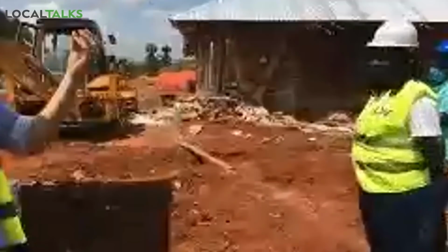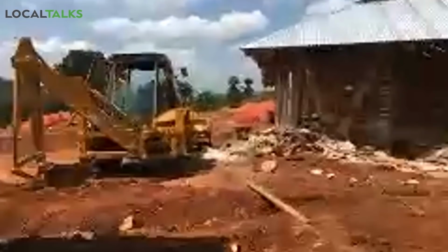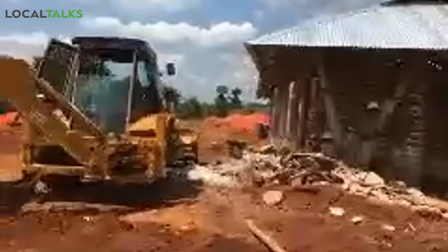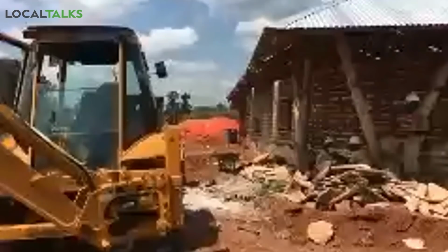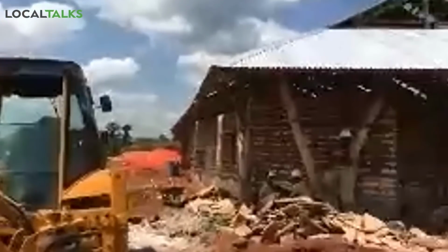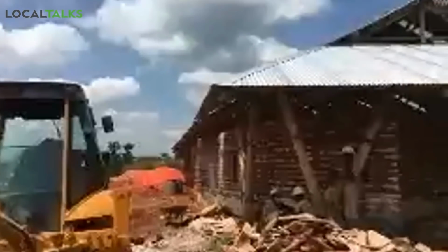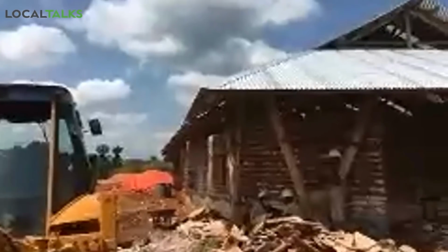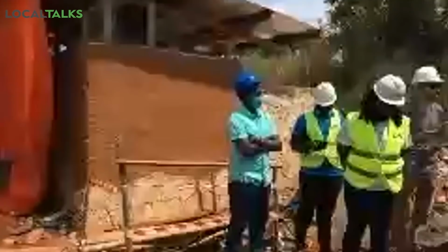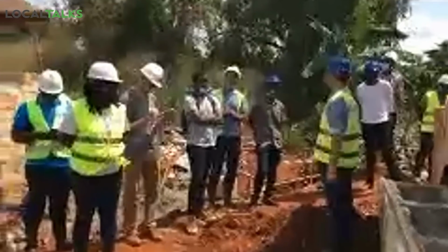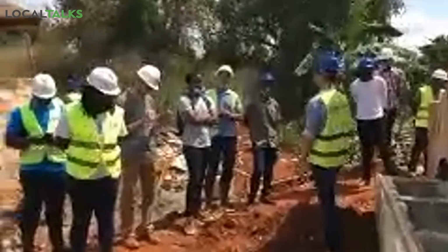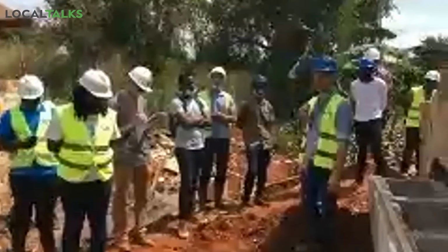That spout will have some chains hanging down, and then we are making some very beautiful earthen concrete receptors that resemble a little bit the traditional village rainwater collection tank. Through that, we are going to collect water. We will have a pipe running along each side of the building, and then we are running a collection pipe all the way down the site to a centralized rainwater collection tank. That's the design in short.